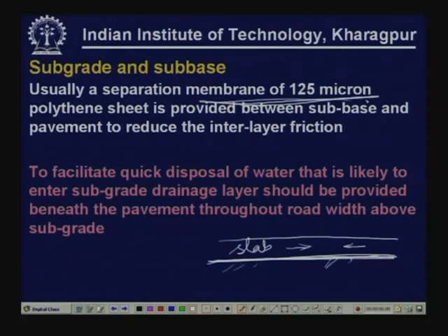But by doing this, if there is a dry lean concrete base placed over subgrade, as nowadays a dry lean concrete base is recommended, and over the dry lean concrete base the concrete slab is placed, then the dry lean concrete base or subbase also has significant strength. When the concrete slab is roughly bonded with the dry lean concrete base, it can mobilize more strength out of the DLC, and that can reduce the overall wheel load stresses.